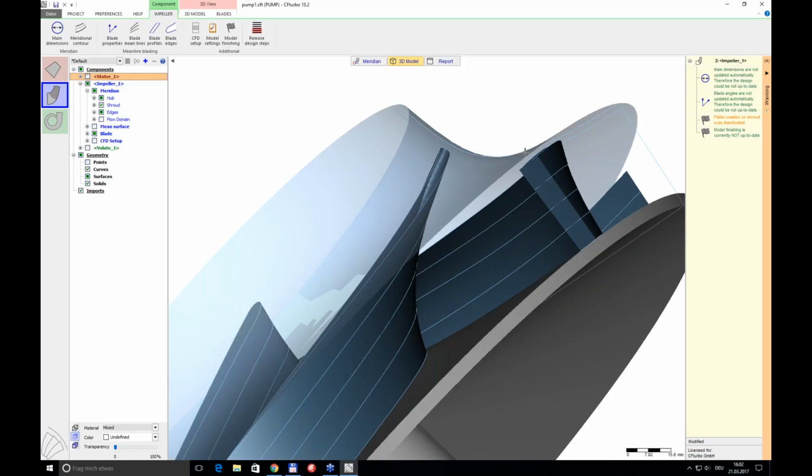For example, which formats like STEP or IGES can the TurboMachinery CFD software support? From Saresh. Yeah, I will quickly answer this. Currently, the TurboMachinery CFD supports only STL format. It's so simple. Only STL, stereolithography. It's very standard. Almost all preprocessors or CAD systems can export in STL. So we stay with STL, it's just the STL for now.